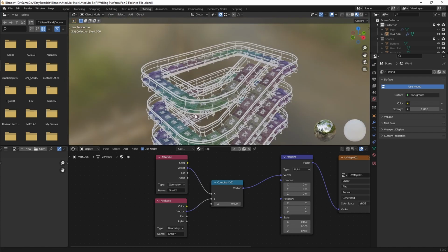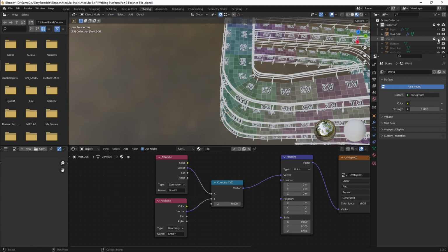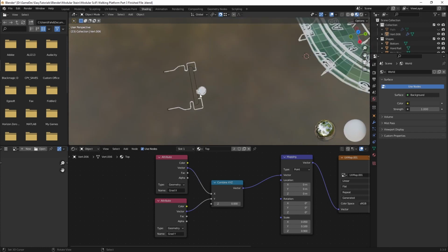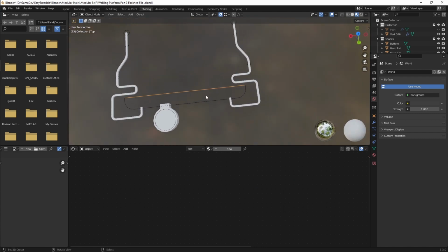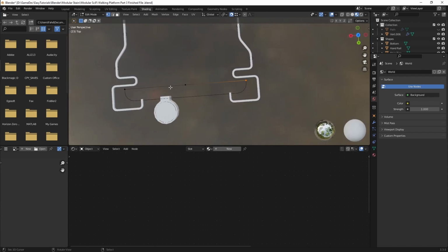That is because in the shapes, when we created the top layer, we didn't have enough mesh or vertices to display these textures properly. So let's go into the edit mode. Currently the top section has only 3 vertices, so let's select these and subdivide, and let's increase the subdivisions to about 5.